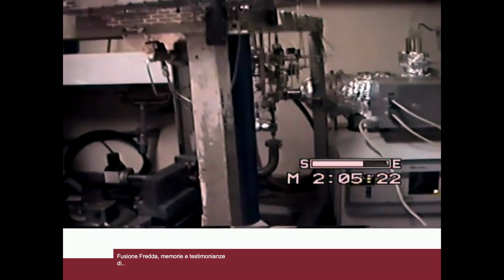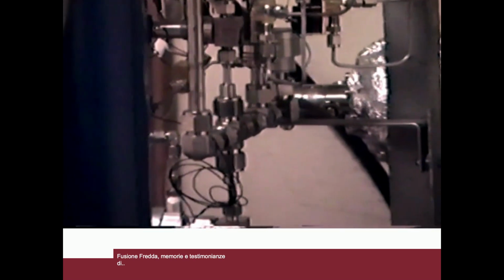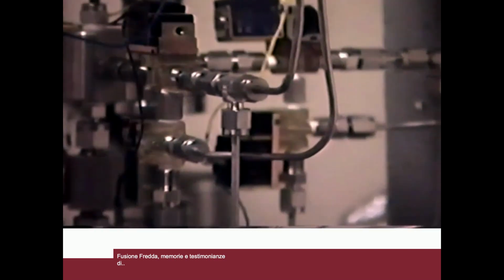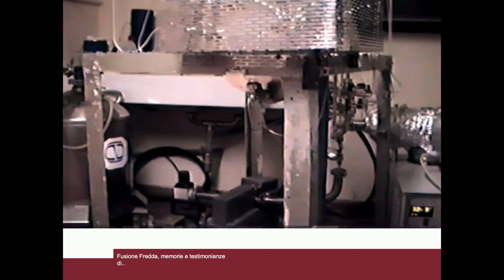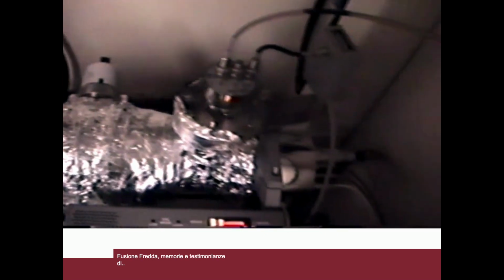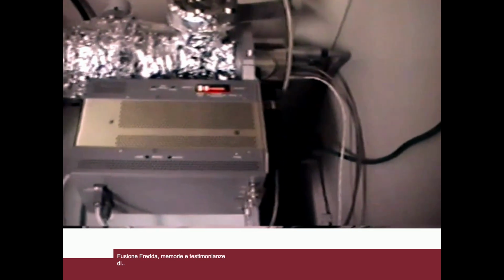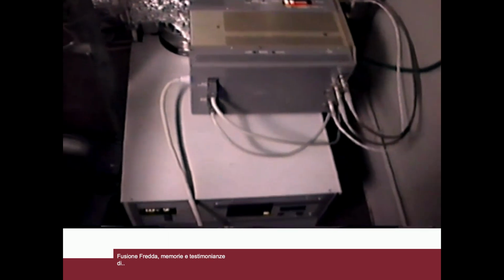The introduction of gas into the mass spectrometer is regulated by a low vacuum system such as to create the optimal working conditions in the spectrometer chamber. Upon command, the inlet needle valve into the spectrometer opens. The spectrometer chamber always works around a pressure of 10 to the minus 9 millibar. The pressure gauge inside the chamber controls the closure of a needle valve if the pressure rises above a preset value. It can be observed that all the connections are made with Swagelok pipes to ensure